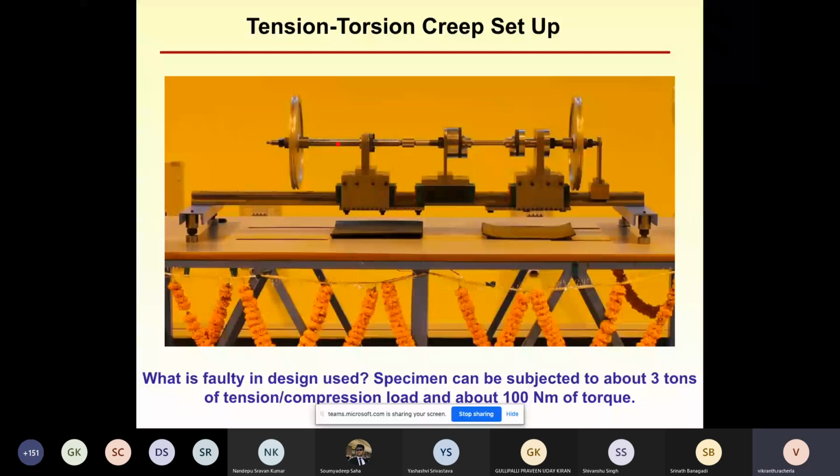The pulley diameter is 300 millimeters. The pitch of the ball screw is 5 millimeters. So for 1 mm downward movement of the weight which is hung around the pulley, what will be the corresponding linear motion achieved for the ball screw? One rotation of the pulley will lead to a movement equal to the lead.